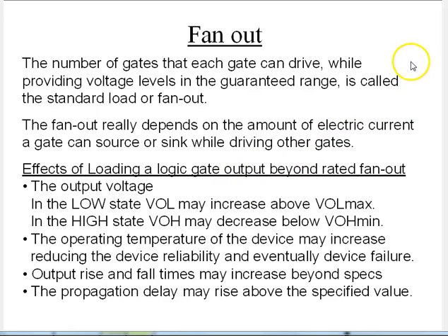So if you're going to have an output of a NAND gate, how many other devices can you have that go into it? What can happen is if your load is too high, then it can't actually source or sink the right amount of current. It's sourcing current when it's trying to drive the signal high, it's sinking current when it's trying to drive the signal low. And if we have too much load there, then the low state may increase above the maximum acceptable value for an output low.